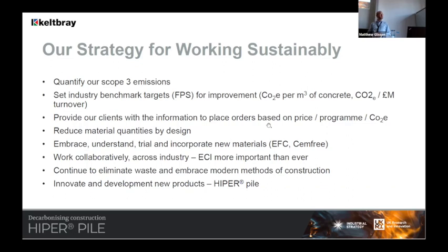So we use that for CFA piles. There's about 240, 250 piles, 600 millimeter and 750 millimeter diameter CFA piles, to around about 25 meters deep. We've done a lot of testing and trials to lead up to that point. A lot of lessons learned along the way, primarily that OPC doesn't mix well with the Wagner EFFC material. When we were changing from one mode to another in the back of the CFA rig, those two concretes mixed in the lines and everything got blocked within about 10 minutes. So very highly reactive in terms of setting times, especially when mixed with OPC. I'll talk a little bit more about that in a second.